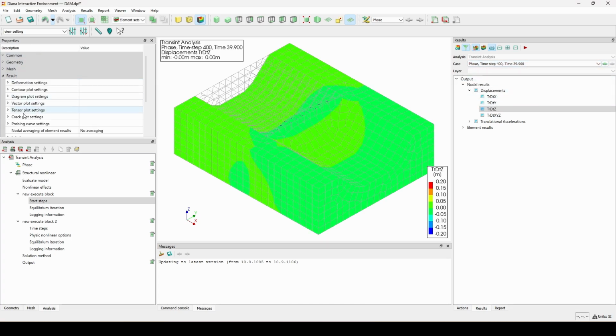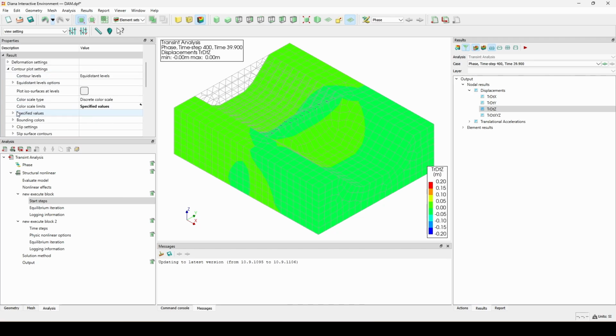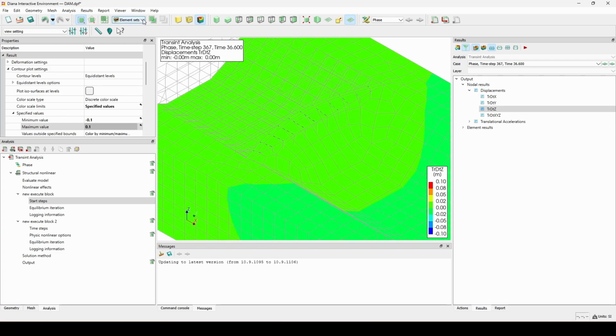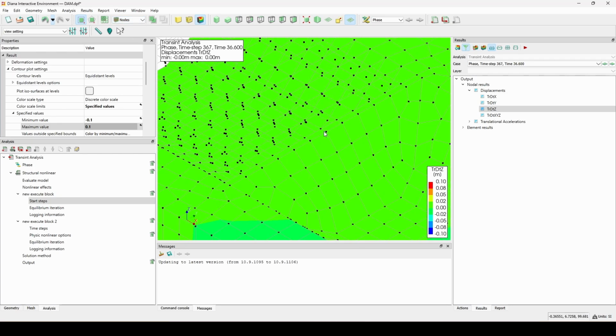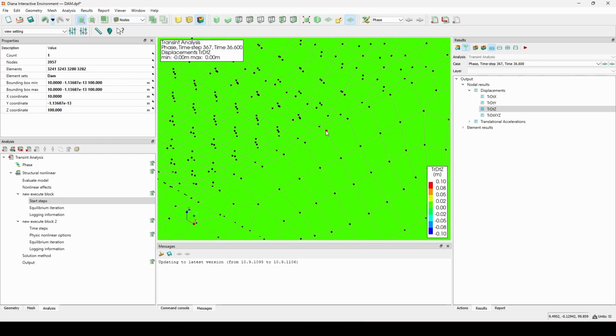As you can see, you can also define the control limit in the properties toolbar. For example, you can define different numbers for the model, and these are the data. Also you can set the selection mode to node, select one node on the dampers, and show the table.